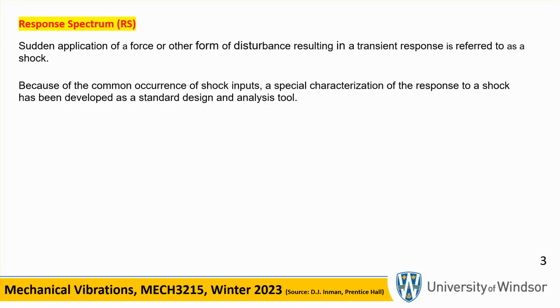For example, if you hypothetically drop a hammer on a table, the table starts vibrating up and down, and this load that you just introduced by dropping the hammer on the tabletop is not an impulse, because it is a sudden application of the load, but it doesn't go away. That's why things like that are also called shock loadings, which result in a shock spectrum, by the way.